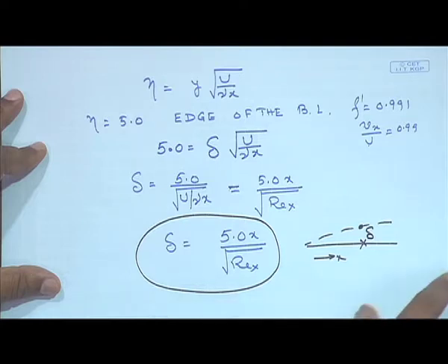Let us quickly look at some other important parameter which the engineers would like to have, which is to find what is the shear stress exerted by the moving fluid on the plate, or in other words, what is the wall shear stress. Can we use the numerical solution of Howarth to obtain such a closed form solution for the wall shear stress as well? So, we will quickly do that.